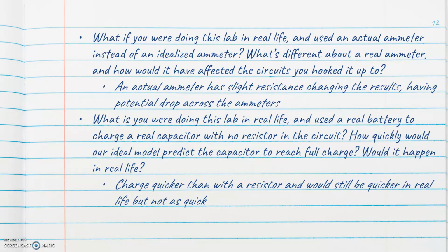For the questions, if you're doing this lab in real life and used an actual ammeter, the ammeter would have a slight resistance, which would alter the result, and you would also have a slight potential drop across the ammeters. So basically everything would be slightly off.